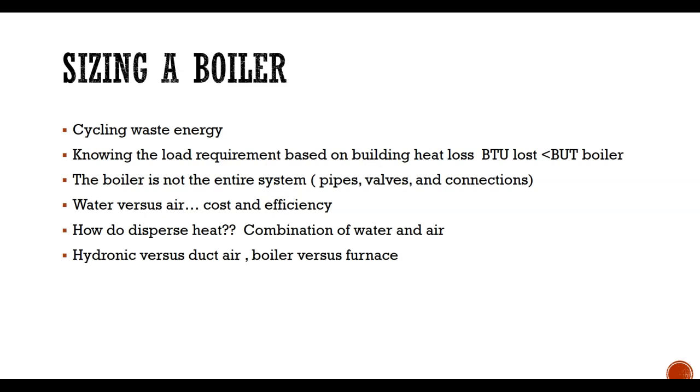Again, I'm still comparing hydronic system and duct air, and boiler versus furnaces. It's a different strategy, and these are the two most dominant ways to heat houses in this area. So you have to always have that comparison, and sometimes it just boils down to personal preference rather than just efficiency. And when we say efficiency, it's very important to know what we are talking about: in terms of money, or energy, or capital cost, or even maintenance.